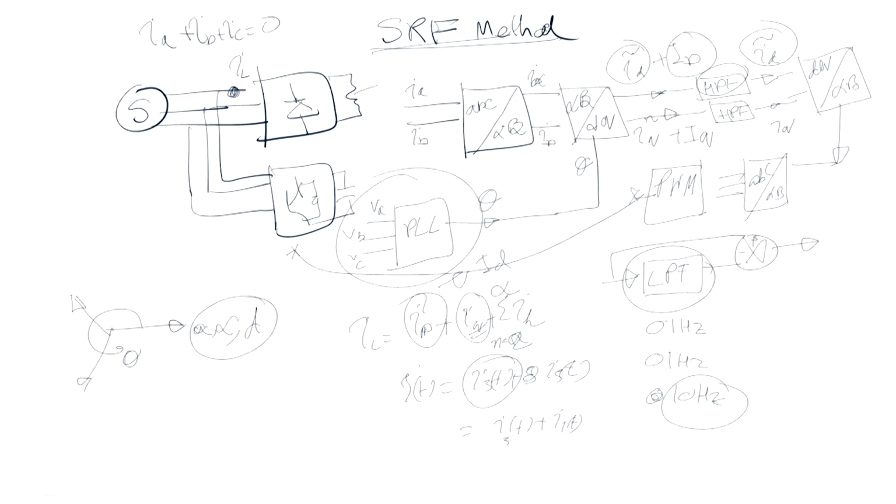The lower the cutoff frequency you set, the more accurate will be the value of delta, but there will be a delay in calculation because this low pass filter requires time for settling, and ultimately we need to optimize. So, we can train this optimization and use this ANN. That is one of the works of the ANN that I am going to present in your case.